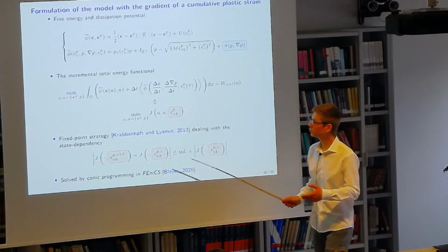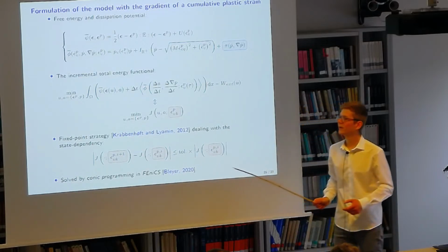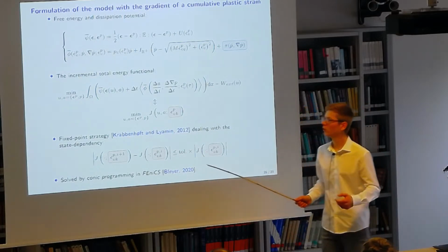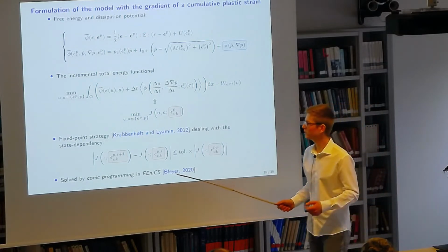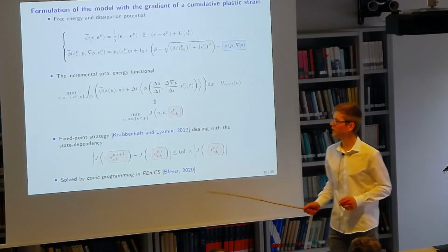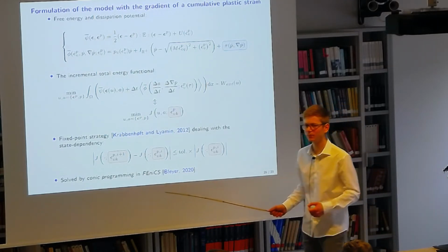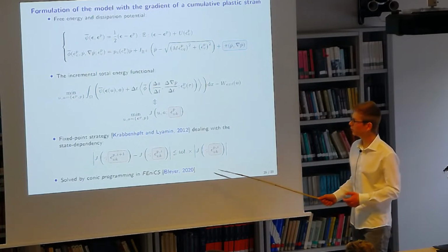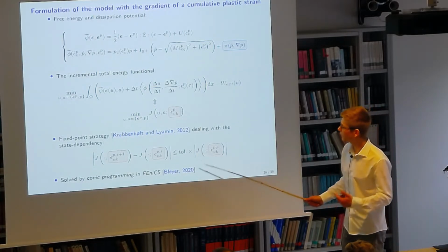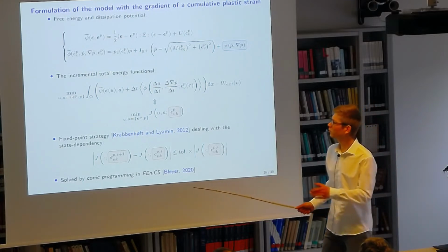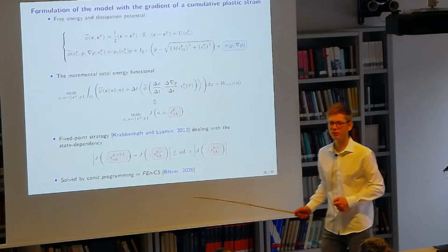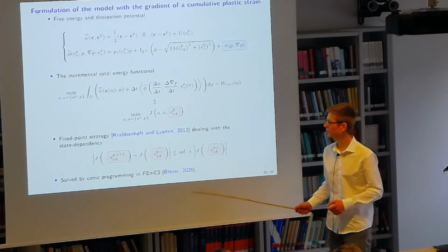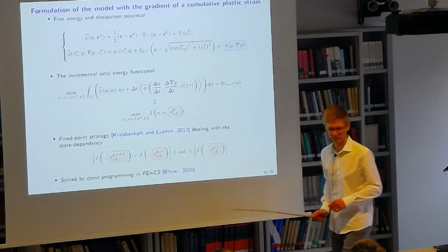So, inspired by a fixed point strategy proposed by Christian Krabbenhøft in order to design a variational resolution of the Cam-Clay model, stress-based and with no regularization approach, we also use the same strategy, which consists, at each time step, in minimizing J over a sequence of iterations in which we iterate over the state dependency by the volumetric plastic strain until we reach a tolerance criterion with a prescribed value. As for the numerical tools used in order to solve this problem, we heavily relied on conic programming and convex optimization solvers, which have been implemented in the finite element method in the library FEniCSx by Jeremy Bleyer.